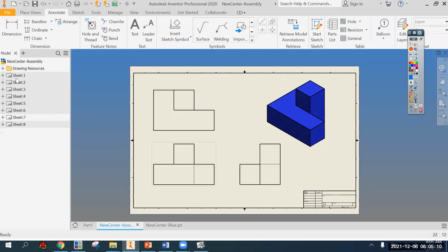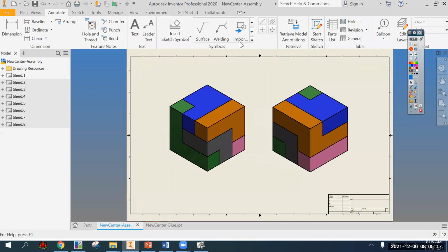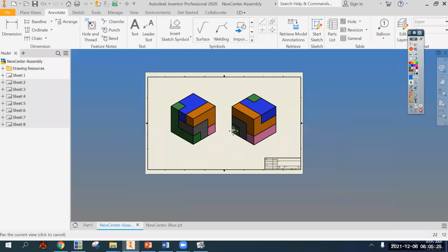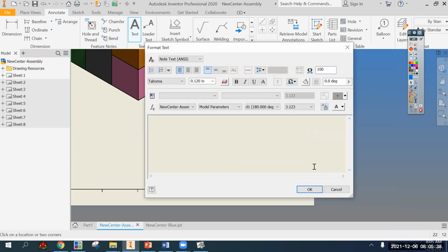Okay, annotate in general just means to make notes. In technical drawings, it's any one of these: dimensioning, part list, text box, that sort of thing. The easiest way to do text box stuff is just to put a text element on top of it.